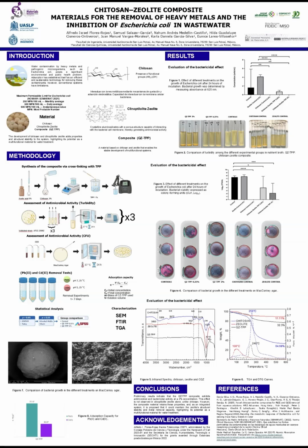The results obtained demonstrate that the composites have high potential for the removal of lead and cadmium, with maximum adsorption capacities of 77.1 and 30.07 milligrams per gram, respectively. Infrared spectroscopy analysis confirmed the presence of functional groups characteristic of chitosan and the structural bands of zeolite. Thermogravimetric analysis revealed that SB3-P046 exhibits greater thermal stability than pure chitosan due to its interaction with the zeolite and tripolyphosphate. Overall, the composite represents a promising, sustainable, and environmentally friendly alternative for the development of water treatment technologies capable of simultaneously removing chemical and biological contaminants.